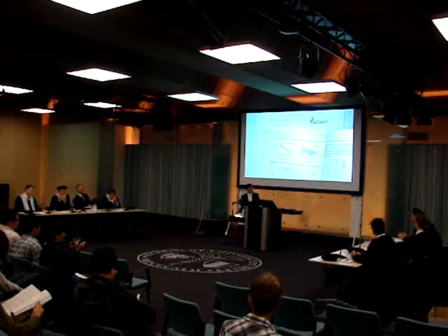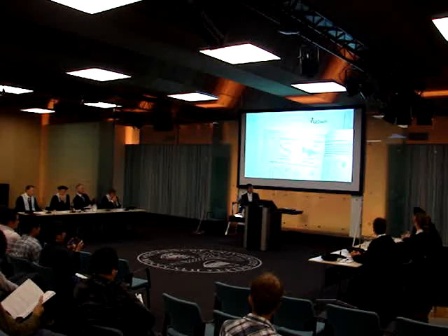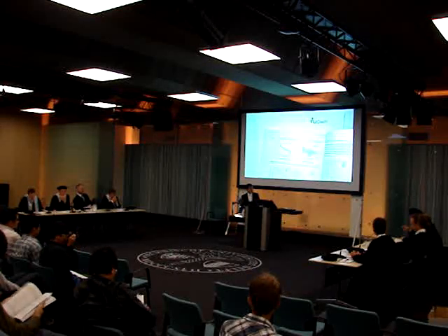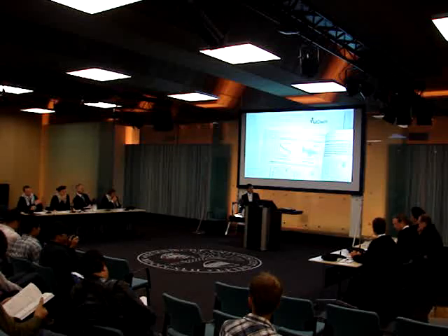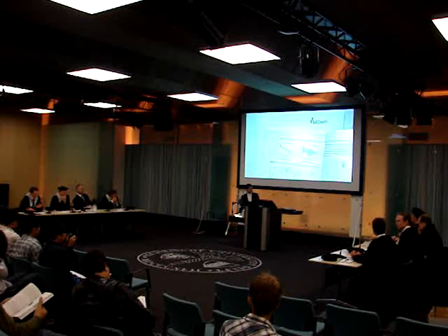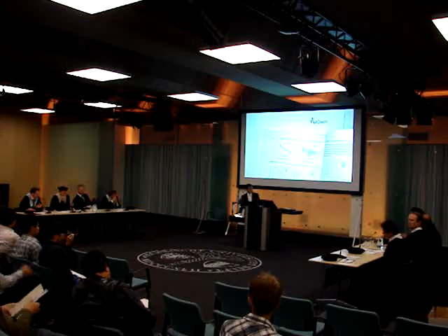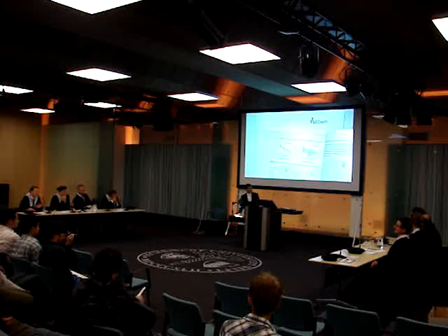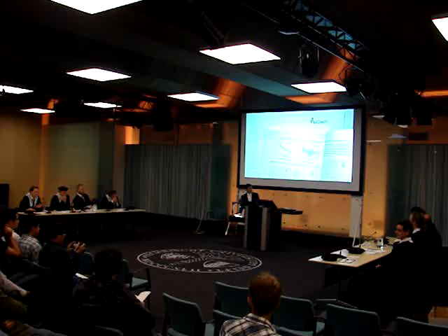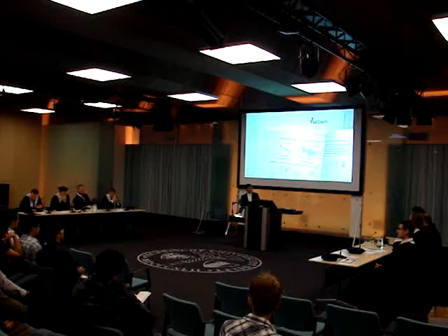This macroscopic constitutive law could be derived from a statistical homogenization of the problem with a macrostructure on an RVE of particular size. So that at the macro level, I have a constitutive law providing an expectation and standard deviation, and eventually also a random spatial correlation.